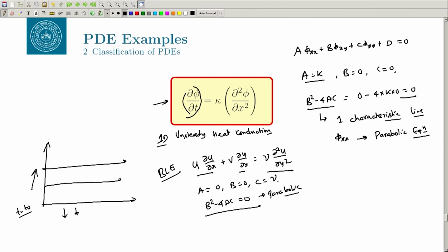If you want to understand the parabolic equation, let us look at this boundary layer equation here, and this is how your boundary layer is developing. Okay, this is your delta, this is your L, right. What a parabolic equation says is that whatever is happening in the future depends on the immediate past. So, you put a disturbance somewhere here at the edge of the plate, with let us say this is L equal to 0, but once you did that you forget about this. Your domain of influence is always on the right side.